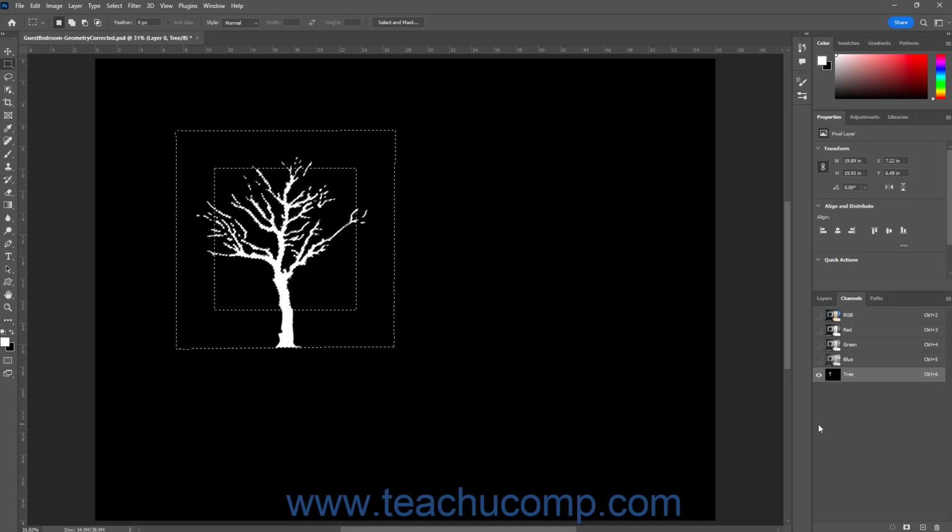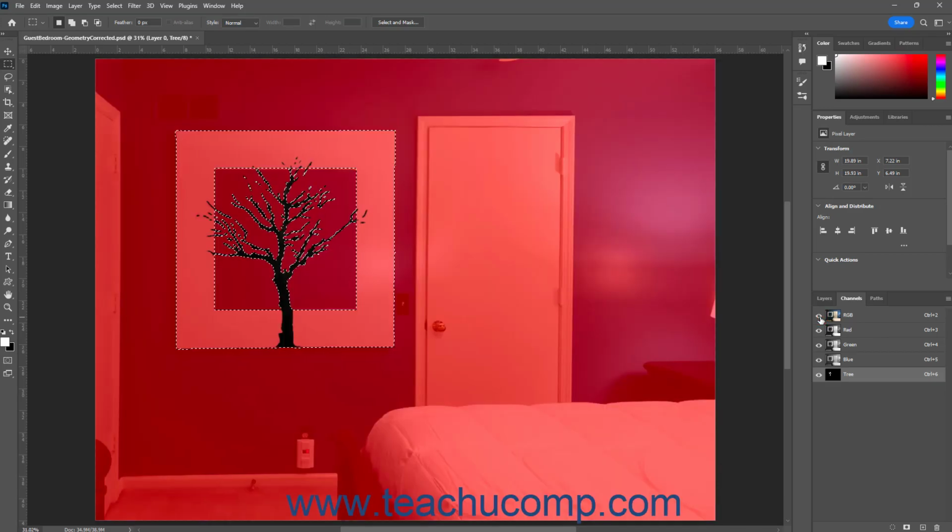After deleting an alpha channel in the Channels panel, Photoshop should automatically select the Composite channel again to let you edit the image file. However, if needed, to select and restore the visibility of the composite color channel in the image after selecting an alpha channel to delete and then changing your mind, click the composite color channel's name, usually RGB or CMYK, at the top of the Channels panel to select it and its associated color channels.